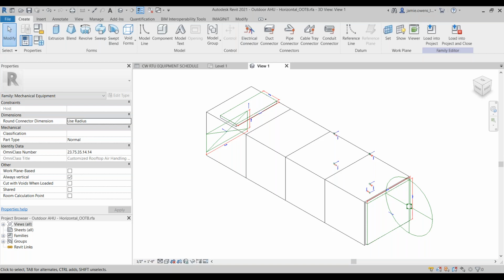Okay. Does any of this work with Revit LT, or is it only for full Revit? Unfortunately, the process of doing it manually is available in Revit LT. Now, Revit LT doesn't offer mechanical systems, but from the components perspective, it has the capabilities. As far as using the add-in, unfortunately, Revit LT does not support add-ins, so that would not be available. So you could do it, but you'd have to do it manually.